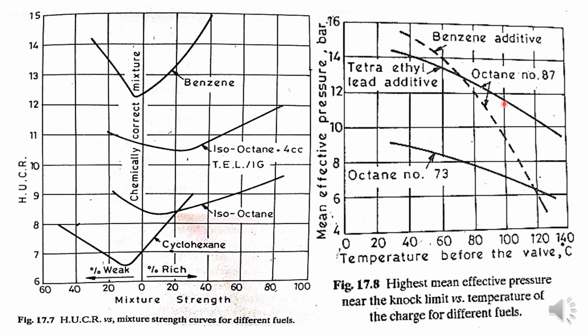With high octane number the knocking tendency is reduced as the octane number increases. You can see that knocking tendency is reduced and pre-ignition tendency is also reduced at a very lean mixture. We can see rich mixture and very lean mixture. The tendency can be reduced, and hence we can use high compression ratio, and mean effective pressure can be increased. So this is about your basic fuel.